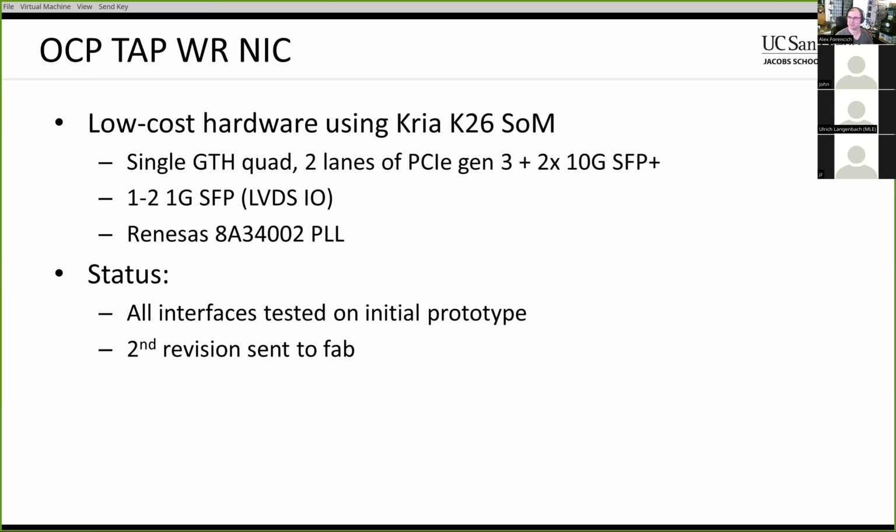It's motherboard dependent, I suppose. From looking at a bunch of the existing dev boards from Xilinx, Intel, everybody, quite a few are definitely implementing things incorrectly. But interestingly enough, a lot of them don't have any pull-ups or pull-downs at all, which is kind of what the PCI spec is going for, right? I can't remember what the spec is, but it's like a few microamps that you're allowed to source or sink, and if you go above that, then it's potentially going to be a problem. So, yeah, I think on the board that Julian laid out, we had like two 5K pull-ups or something.